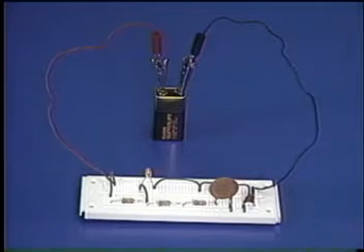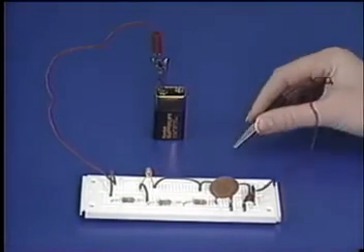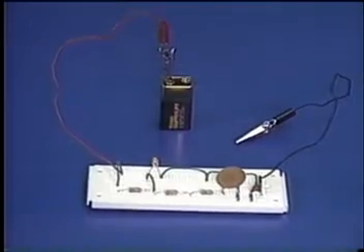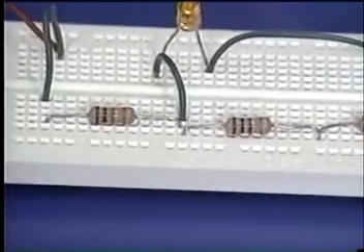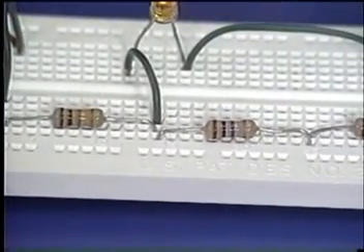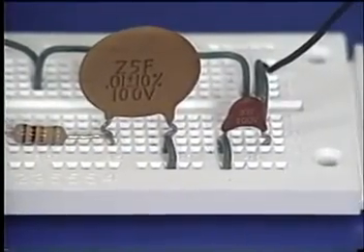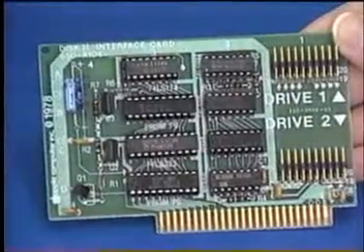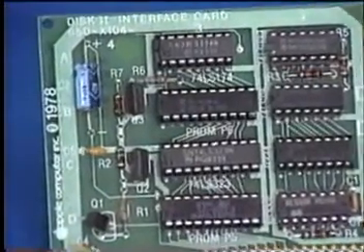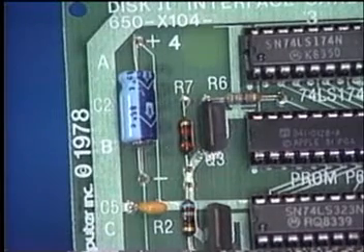There are a few points that you should keep in mind when performing continuity checks. First, before testing for continuity, be sure that the power to the circuit is off. Second, circuits with resistors may give misleading results. Low-value resistors will provide continuity and high-value resistors will not. Third, circuits with capacitors or any other component that stores energy cannot be tested for continuity. Lastly, components connected to complex circuits, such as those on this PC board, cannot be checked for continuity without first being removed from the board.